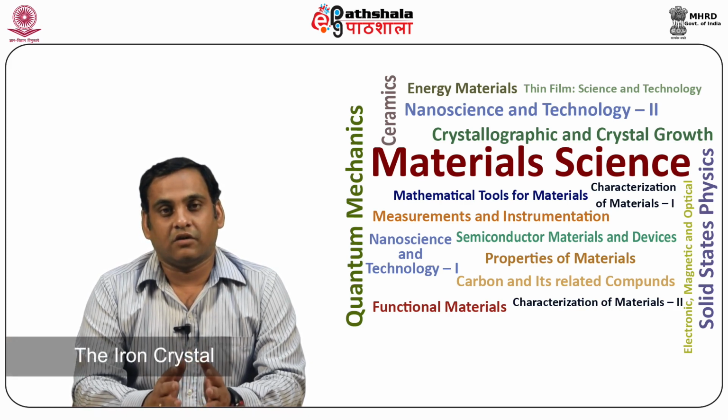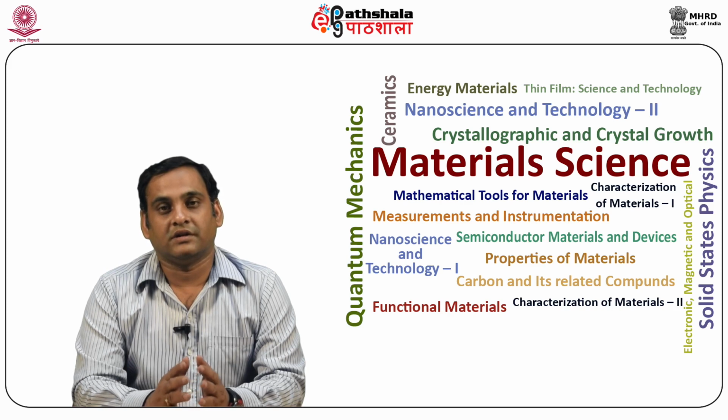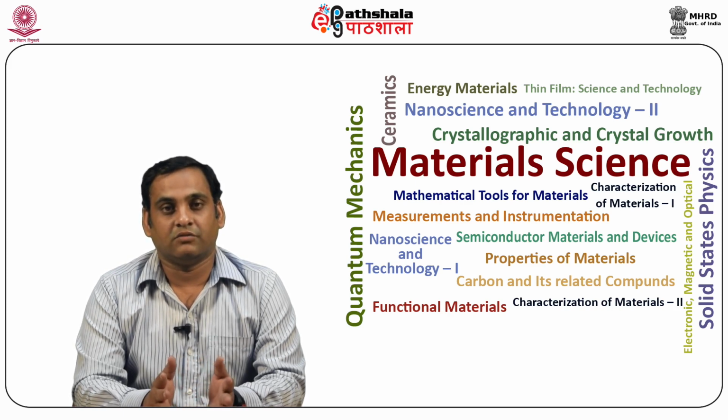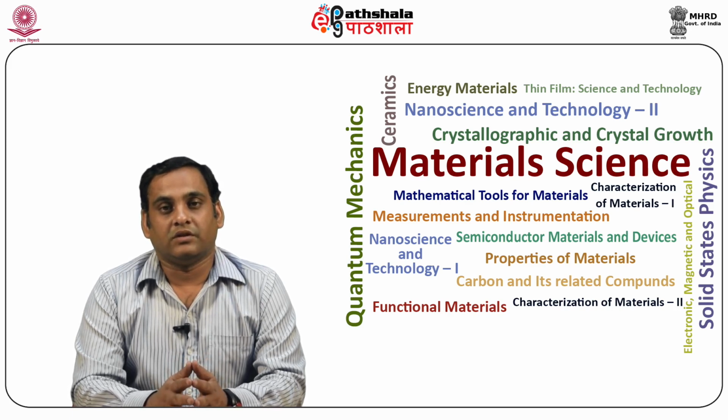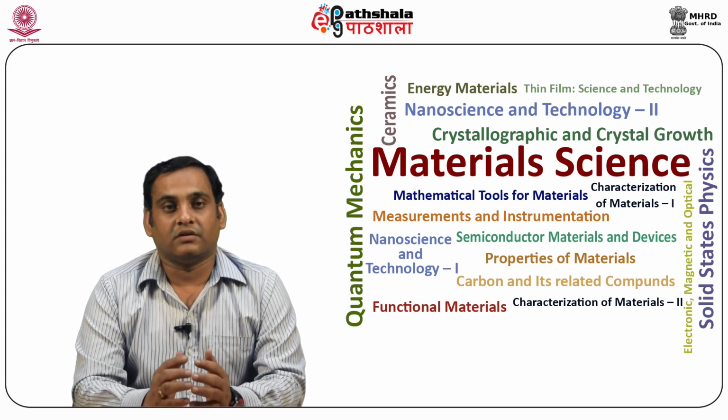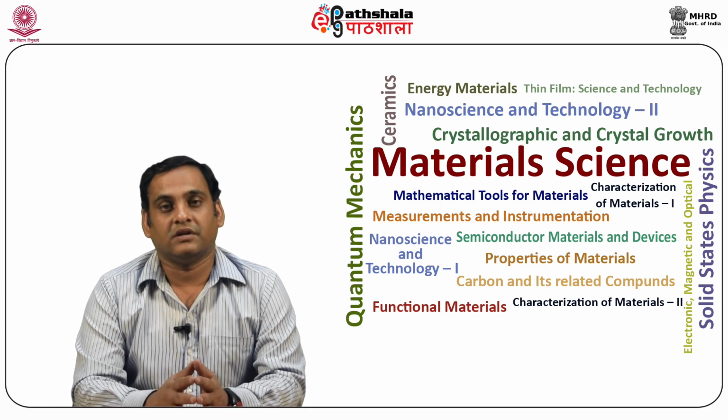The iron crystal of figure 2a has only 90-degree walls. Nickel, which has 111 easy directions, can have 180-degree, 110-degree or 71-degree walls. Non-180-degree walls are often called 90-degree walls for brevity, whether the actual angle is 90, 110 or 71 degrees. The domain structure of a real single crystal is normally such that both 180-degree and non-180-degree walls exist.